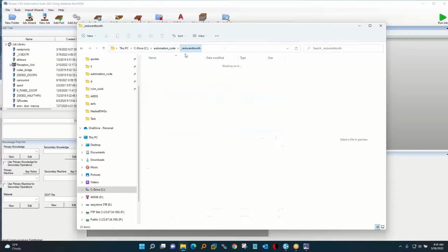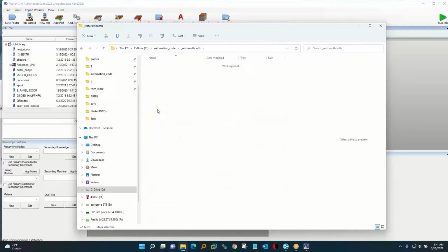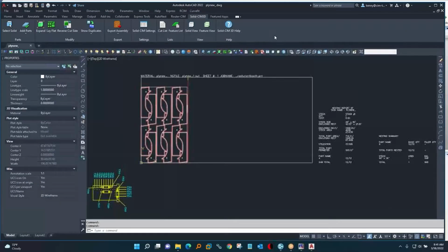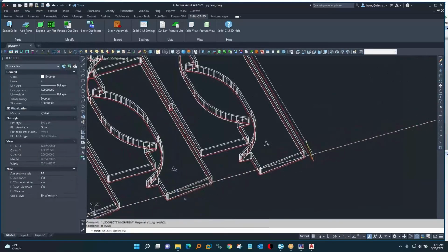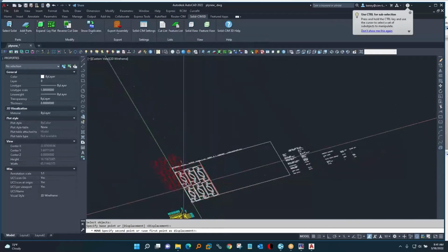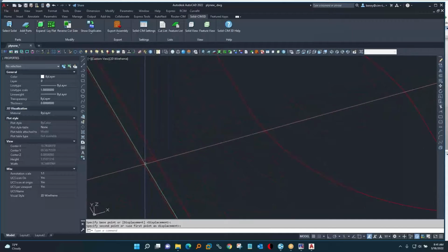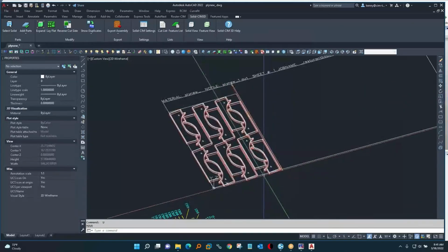So I got 11 individual NC code files, and then this many of the NC code files here, another 8. So we've got 19 programs that were generated, and it saves the drawings of each one of the nests so that you can edit these and drag other parts in there. For example, there's my parts nested, and this is using what's called a tool stay down nest. We've got tool stay down, common line, 2-sided nesting. See, the tool stays down and connects from part to part without lifting up. There's an overlapping bridge, and that can reduce the overall cycle time dramatically.